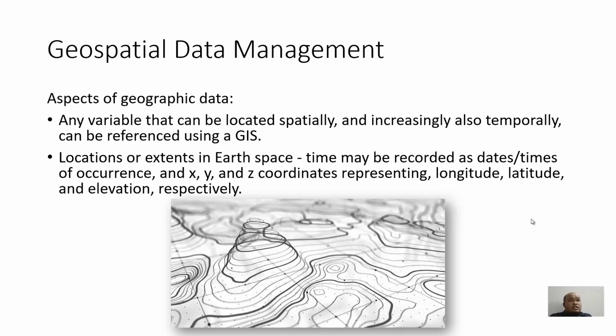the WGS 1984, World Geodetic System, produced in 1984. So that system is widely available and widely understood by many GIS practitioners. So if you have a piece of map, right, that means you actually have the projected coordinate system.